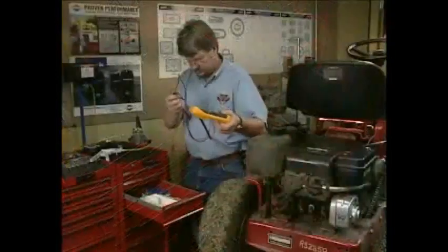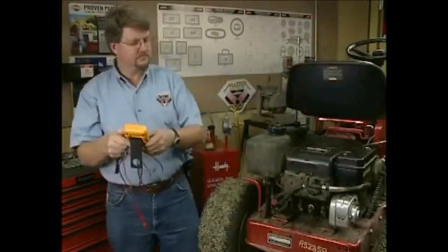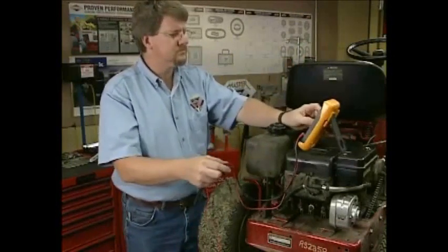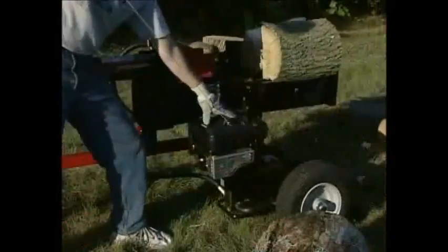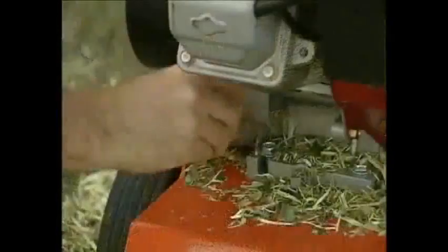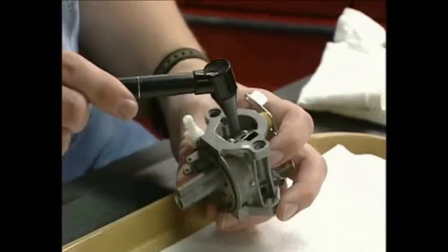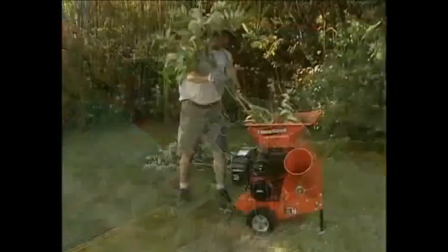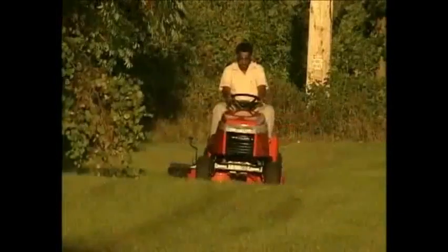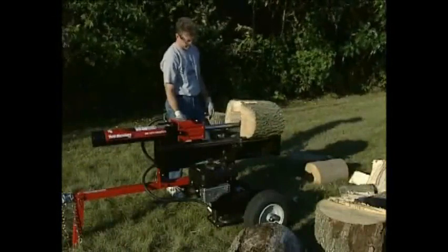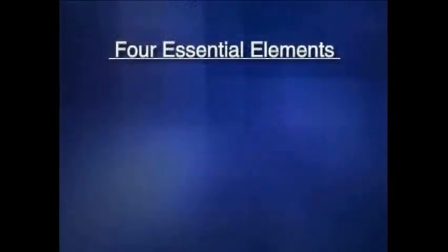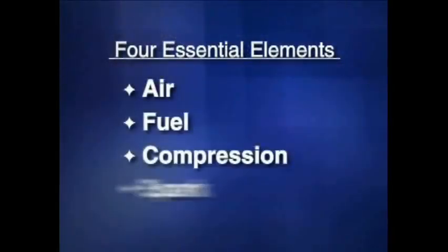However, those aren't the only things you need for diagnostic work. You also need experience, a clear understanding of what the symptoms of the problem are, and knowledge about what causes them. During this update, we're going to list the common symptoms that cause warranty and service-related issues for carburetors. Then we'll investigate the many causes of those symptoms. To help us better understand carburetors, let's review the 4 cycles of a properly running engine and carburetor. 4 elements are required in an internal combustion engine to allow it to run. Those elements are air, fuel, compression, and spark.